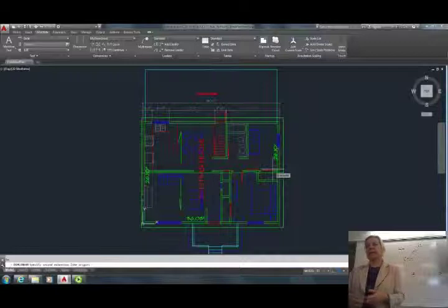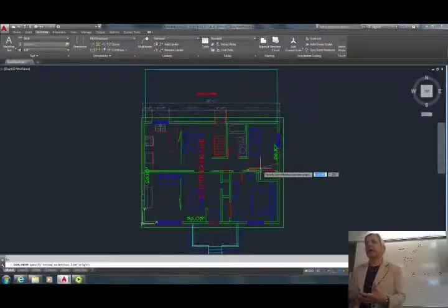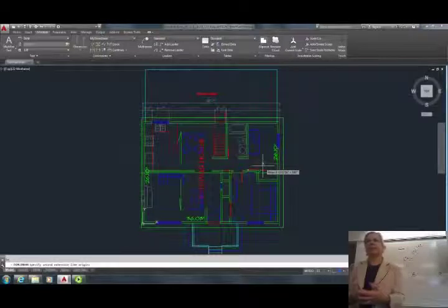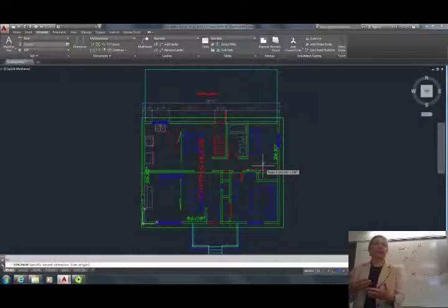Now, another thing about dimensioning the existing house. You don't have to dimension for our project what you don't change. You can just note it existing. Okay? You should be dimensioning really only the walls that are to be built by the builder. So this is where I mentioned that smart designers would have a way of either highlighting or using different colors or different line weights. They would have a way of telling the builder what is to be removed and what is new and what is staying the way it is.